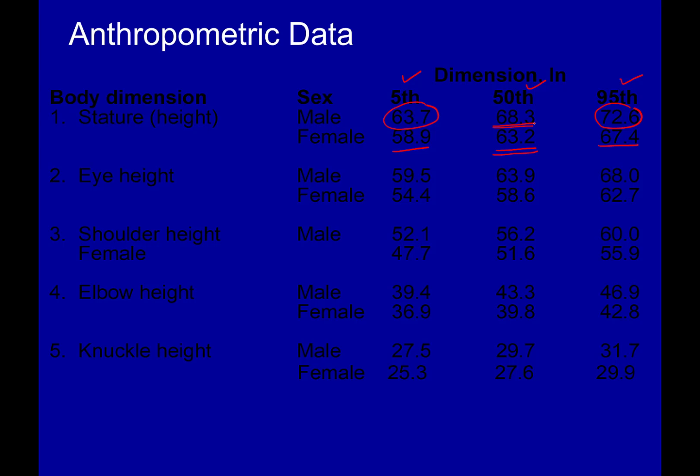So if something is to be designed for averages, things to be used in the public domain, like the benches in a park or the tap location or tap height in a public place, then we use this dimension. If it is about extremes, where both higher and lower dimensions need to be considered in coming out with the design so that every user group can use it, we consider the 5th and 95th.